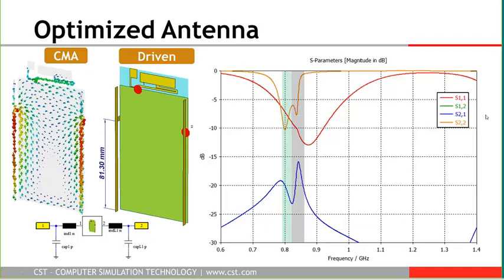The diversity antenna, which is S22, marked by the orange line, is optimized for downlink. So we will use this diversity antenna only for downlink. So the frequency band for downlink in this case is the lower band, denoted by a green column. Coupling between both of these antennas is very small, around -20 dB. The reason is that we excite orthogonal modes which are decoupled from each other.